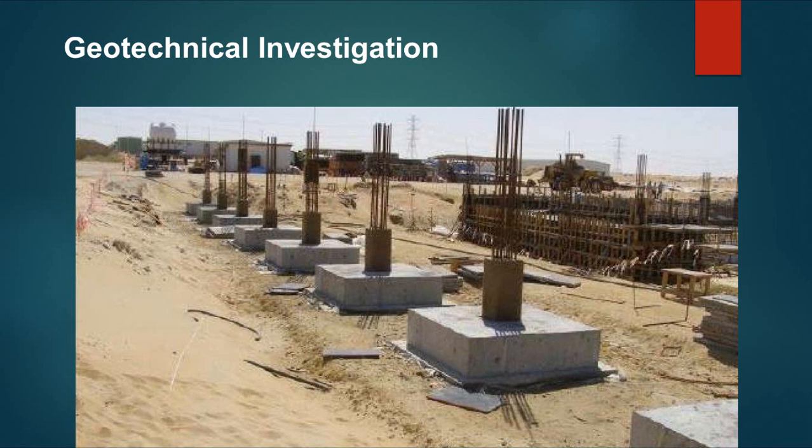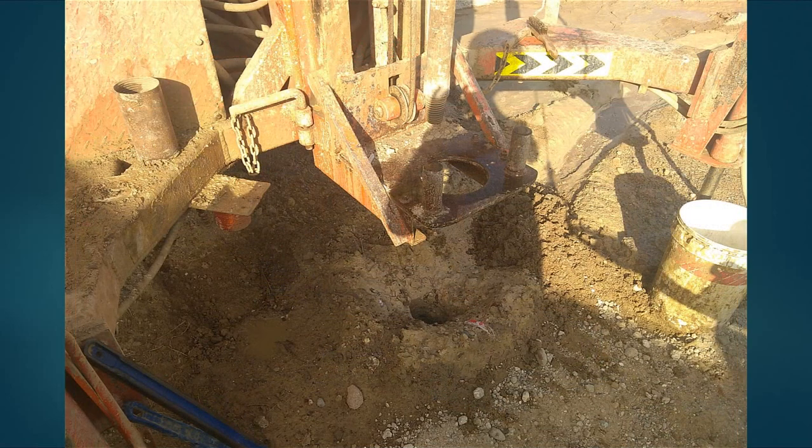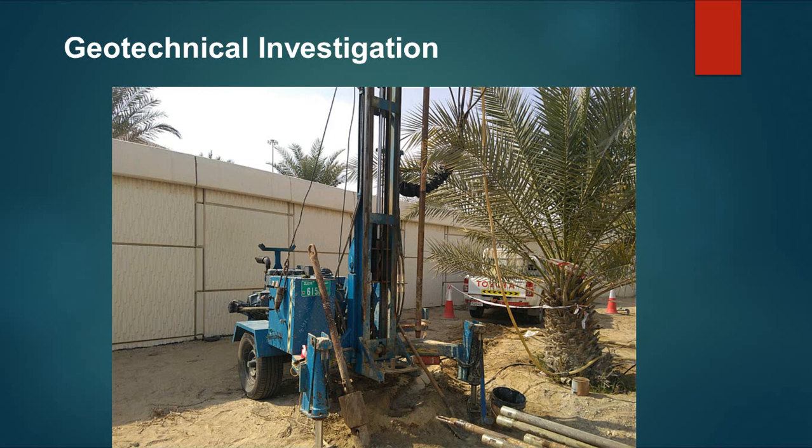Designing of structure requires knowledge of soil chemical and physical properties and geotechnical parameters of soil. This can be achieved by investigating the soil surface and subsurface strata. Several selected boreholes are used for collecting samples that represent different soil conditions for the structure. The sampling method of soil is controlled by soil condition.